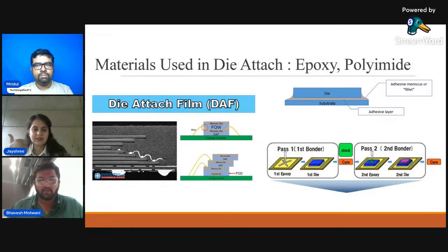Its characteristics: it's a high temperature, chemically stable polymer, applied as thin films or paste. It's excellent as an electrical insulator, and flexibility is much preferred here. Advantages: it's more thermally stable than epoxy, where that was not prioritized; here it is. Then excellent chemical resistance and long term reliability, even in harsh environments.